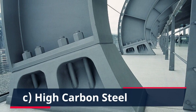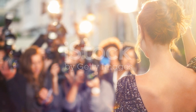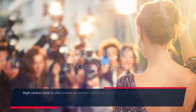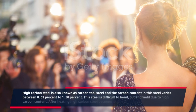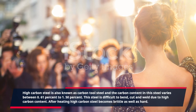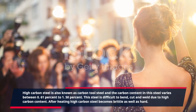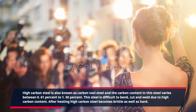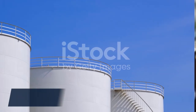C. High carbon steel. High carbon steel is also known as carbon tool steel and the carbon content in this steel varies between 0.61% to 1.50%. This steel is difficult to bend, cut and weld due to high carbon content. After heating, high carbon steel becomes brittle as well as hard.